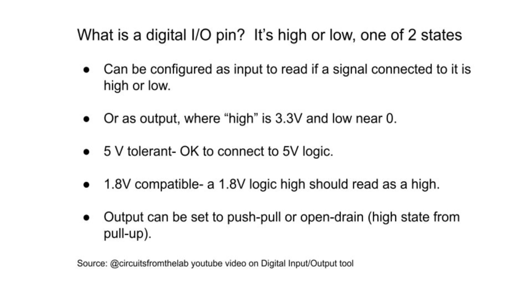The pins are 5-volt tolerant, which means it's okay to connect to 5-volt logic. The 5 volts won't fry the 3.3 volt input. It's also 1.8 volt compatible, meaning that a 1.8 volt logic high should read as a high. So you could use the logic analyzer, for example, to evaluate a 1.8 volt circuit.